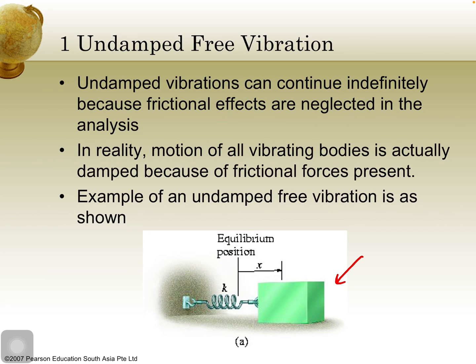So this is an example of free vibration, and it is undamped, because we consider that the floor surface has no friction. Again, we have the stiffness k, the displacement, which we can consider as d or x, and we also have the mass.